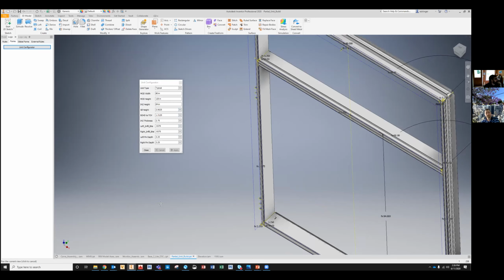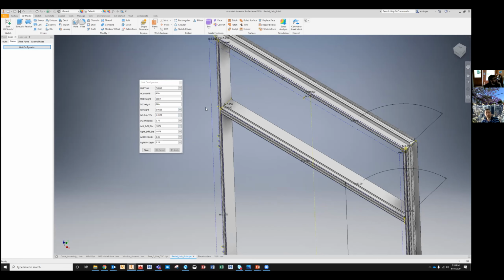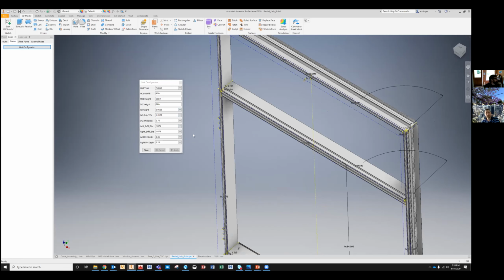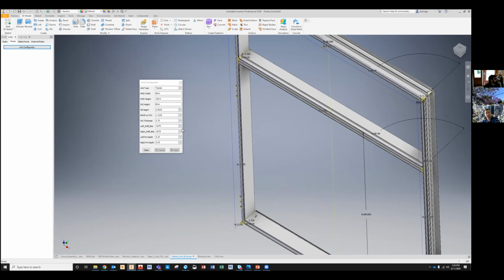This one's also set up so that when we do the infill sketch to extrude the IGUs, we can actually change the bite of the glass on the verticals. Sometimes we have projects where the glass bite is going to be a little different on one side versus the other, and then we can go in and change these. On some of these, I've also built a multi-value list, meaning you can choose preset sizes of items, so you don't accidentally type in a random number that doesn't make any sense.